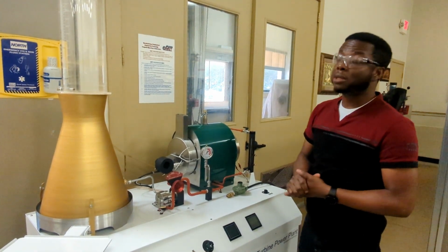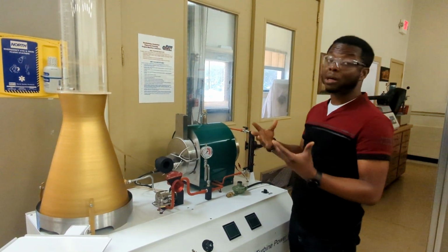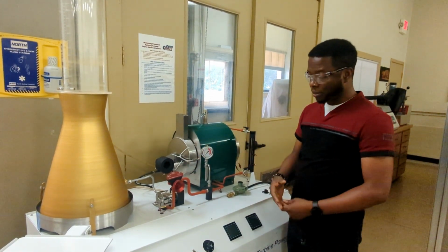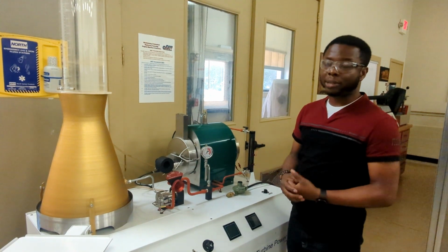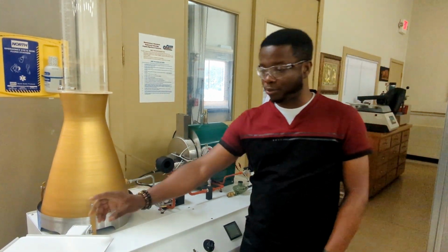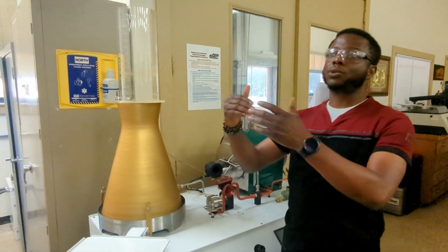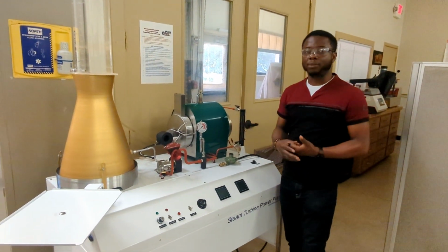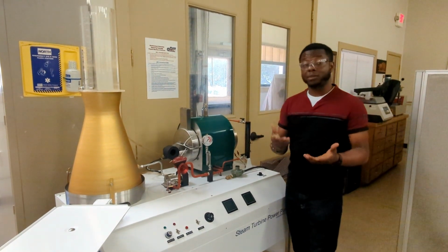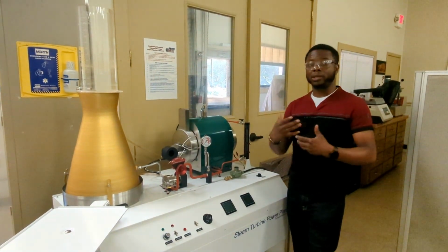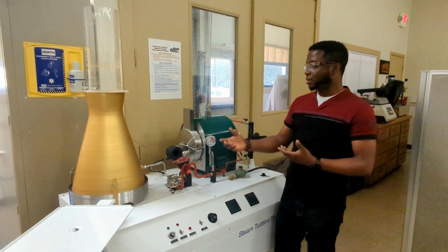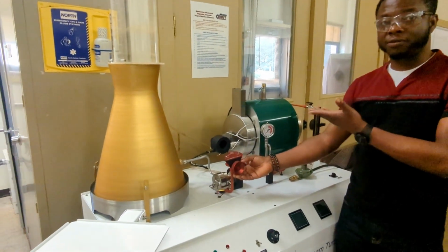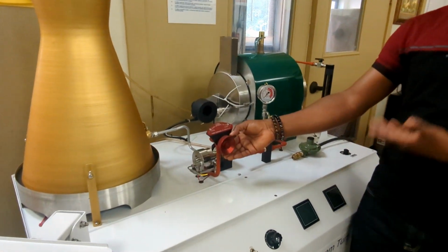Because we need steam power to be able to power up the turbine, this can take more time. By the time we can measure the temperature in the software, it gets up to saturation temperature and it builds up to superheated steam. When we have elevated temperatures ranging from 160 to 180, we can start regulating the steam admission valve gently.